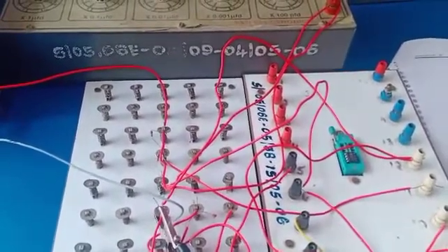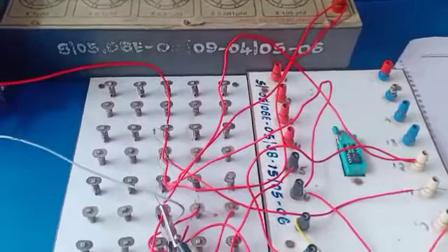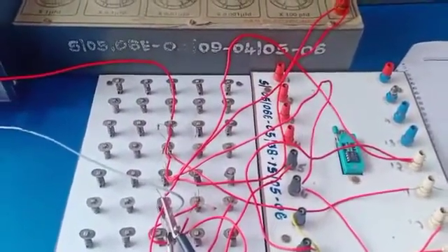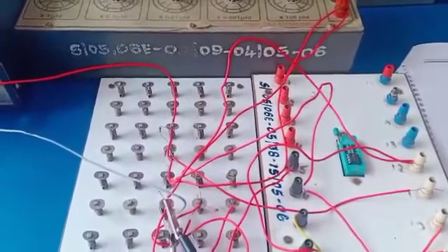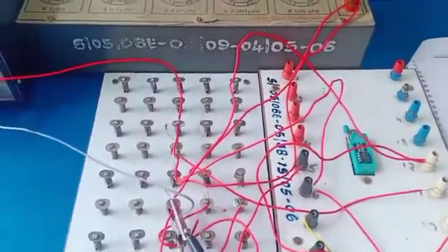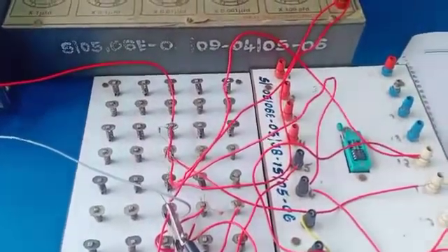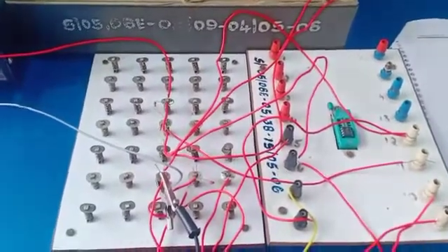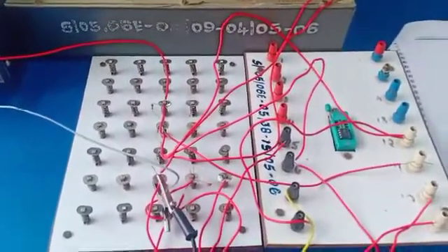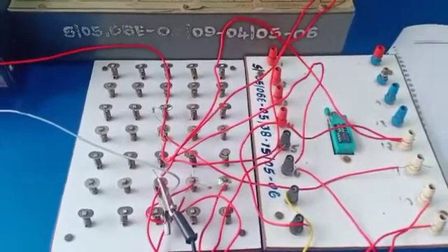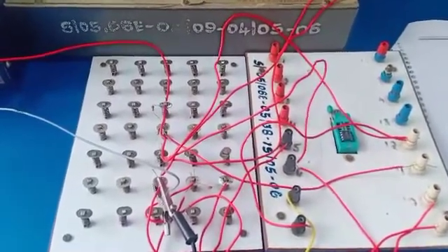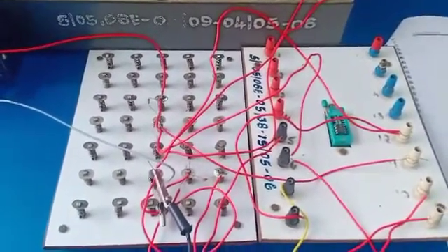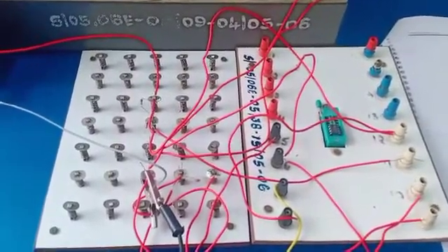In the monostable mode the 555 functions as a one shot. Applications under this include timers, missing pulse detection, bounce free switches, and touch switches. Like this we have a lot of applications under this monostable mode. Astable mode means it is a free running mode. The 555 timer can operate as an oscillator, used in LED and lamp flashers, pulse generation, and logic clocks. These are some applications under this astable.